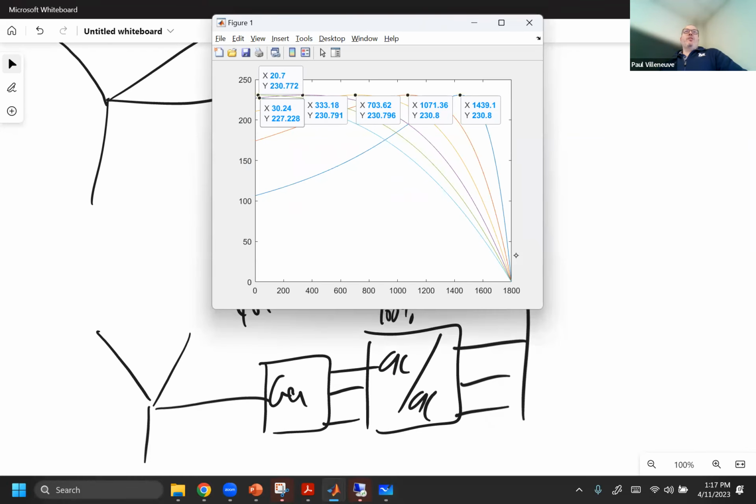But that's how wind turbines used to do it. If you look, I think it's Vestas had something called OptiSlip, one of their turbine designs. I don't think they still make it, but it essentially was putting in a variable R2. They called it OptiSlip. Where do you think the slip comes from? It's the slip equation that we talk about here. And Opti, I guess, optimum slip. So that's where they would come up with that.